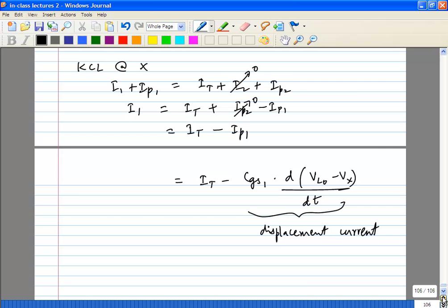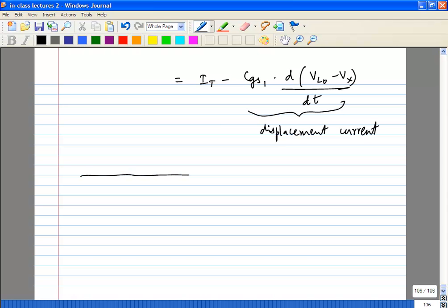And what will the signal at node X look like? That you already know, right? It's going to have all the even harmonics. It's going to look something like this actually. Ideally you want it to be flat. If your LO signal was a very small signal, it will just be the bias, input bias minus VGS of the input transistors. But that is just a DC. If you have a larger signal at the LO, in this case we do, then you will have all the even harmonics coming in at the common node. It looks something like this.